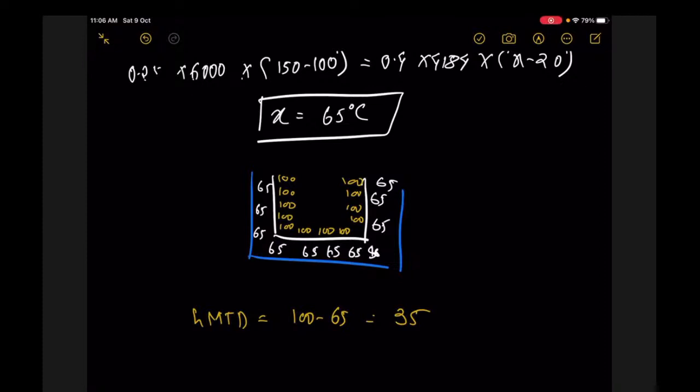Ideally, there may be a little bit of fluctuation in real life, but ideally. That also depends upon how you are doing the mixing, how perfect the mixing the stirrer is doing, and all that. There are various factors on which it depends, the speed, the agitator RPM at which it is running. There are tremendous different ways.